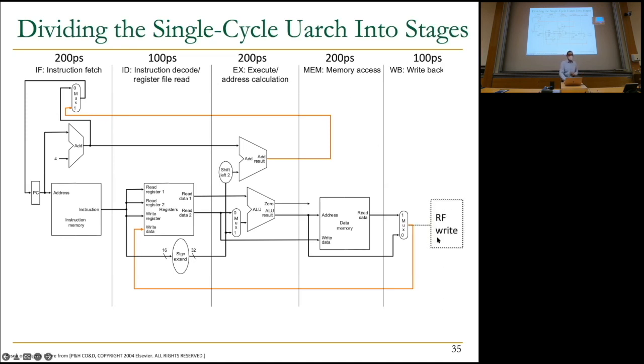And you need to have the resources so that you can write to the register file over here. So basically, we're going to have these loops. These loops are going to cause headaches to us, actually, in the pipeline, as you will see. So ignore these loops for now, but keep in mind that in a single cycle machine, if there's a loop that looks like this, meaning a result is being communicated in some later part of the machine to the earlier part, now, how do you do that becomes important, right? For here, we need to update the program counter. When do you do that and how do you do that? Here, we're going to update the register file. When do you do that and how do you do that? Because you don't want to update the register file here.